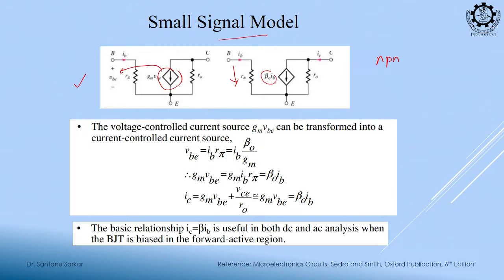You will always be seeing this term small signal, which means two things. One is the signal is AC, and next is the amplitude of the AC signal is small. Why small? Because we have seen that if it is big, the equivalent circuit may get clipped, it gets into the saturated region. That is why we always say this is an equivalent small signal model. Because the overall response may not look like a linear response, but if we break it into smaller chunks, it can always be approximated as a linear expression.